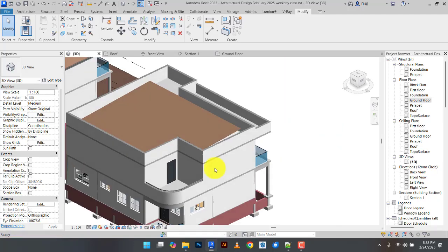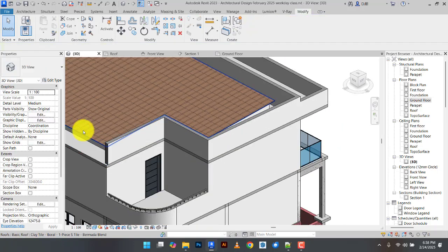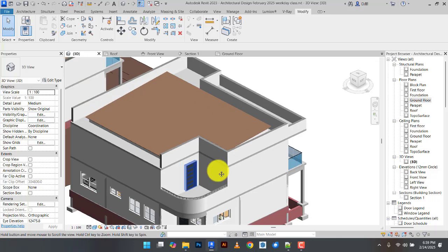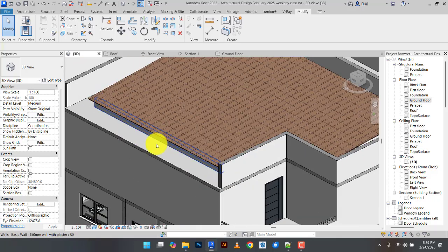Some people get rid of the wall here and extend the roof so the water can drop. Right? You can do it. So just extend the roof back to this point. So the wall at this end needs to come back. Then the roof will sit on it. Then the water can drop down. Some people will do it that way. Depends. Sometimes there's still a wall here, but the wall here is shorter. Then it falls on it, then it goes down.